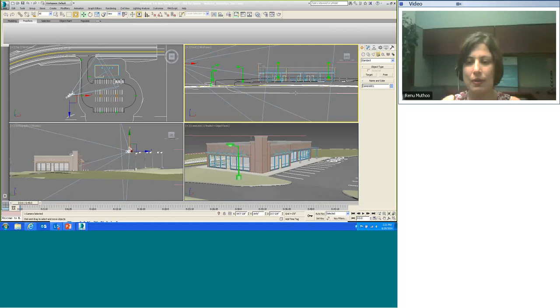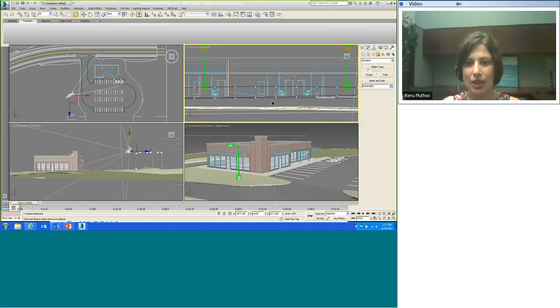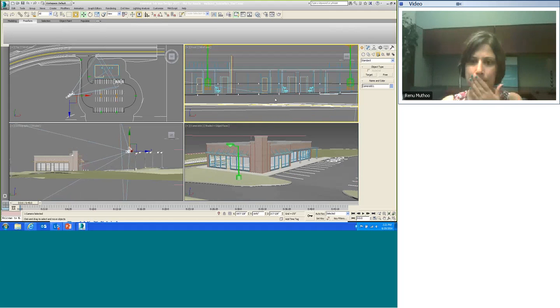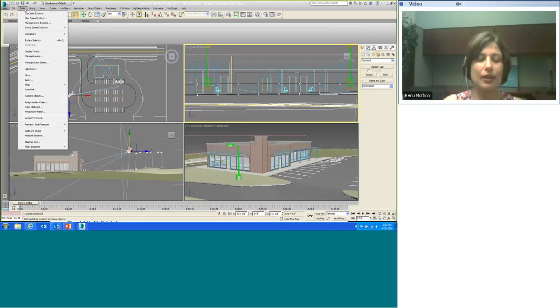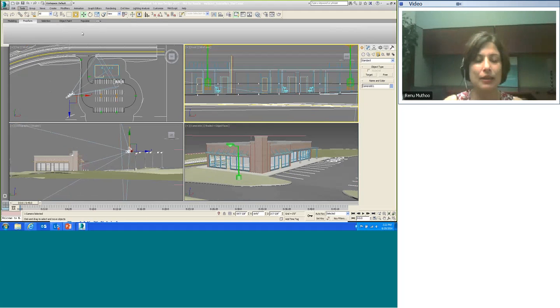So we will go in here to locate the target, but it's kind of difficult to see the target here. So what we can do is we can use the Scene Explorer to locate the target. Now, many of you who have been already working in the 2015 version of the software, this Scene Explorer is kind of new this year. And here we can select, it works very similar to the Select by Name dialog box that we used to open by clicking this button here.